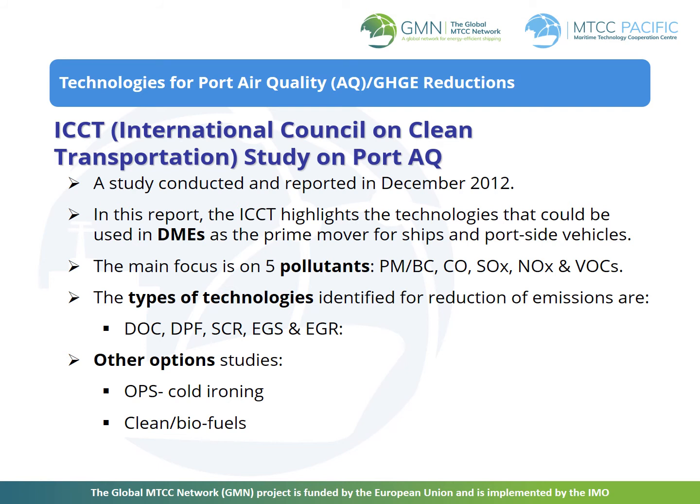Exhaust gas scrubbers. Again, this is a very well-known technology for the back of engines on the exhaust gases path to capture the SOx and prevent them from leaving the engine exhaust. Exhaust gas recirculation. This is a well-known technology that aims to reduce the engine's combustion temperature and thus reduce NOx by circulating part of the exhaust gas back into the cylinder.